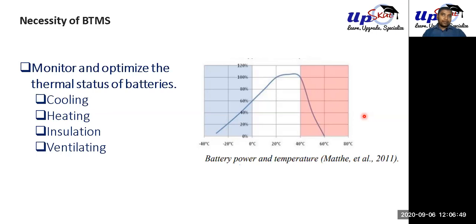Another reason for thermal runaway can be a short circuit, but we are not discussing this right now. We are discussing high temperature. A high temperature scenario is bad for our battery because it will also accelerate the dendrite formation process. Earlier we saw the dendrites. More dendrites are formed during the high temperature scenario. Most dangerously, the electrolyte becomes volatile. It loses its operational efficiency.